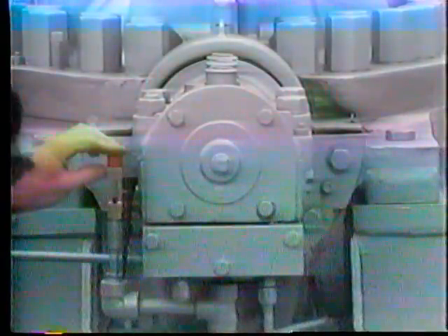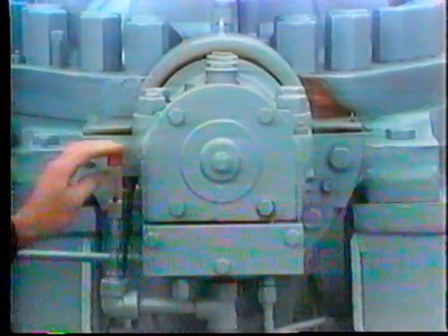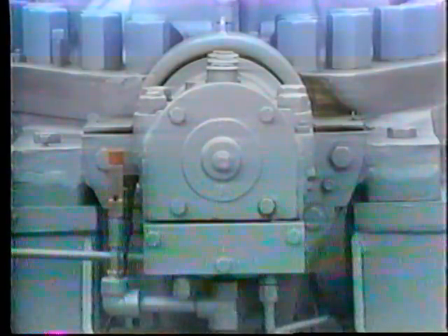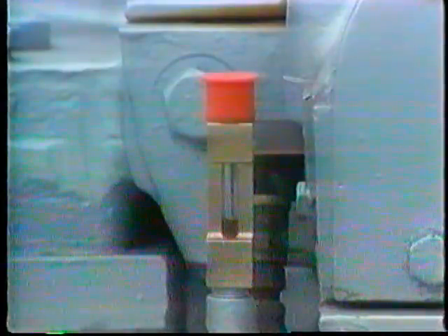If you try to add oil when the machine is operating, however, you may overfill the machine since some oil is spread around inside the housing. When the machine stops, the excess oil may run back out, or too much oil could produce extra friction in the machine. Plain bearings sometimes use a reservoir built into the housing.